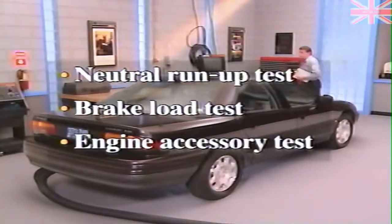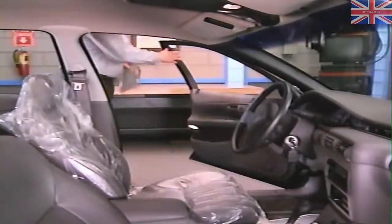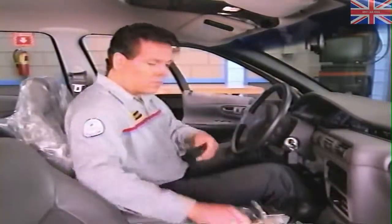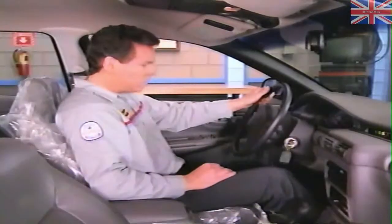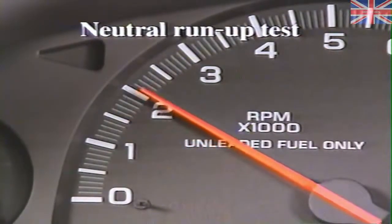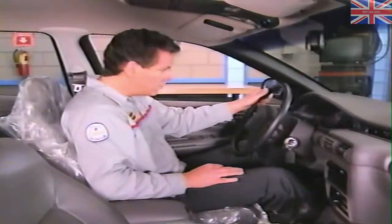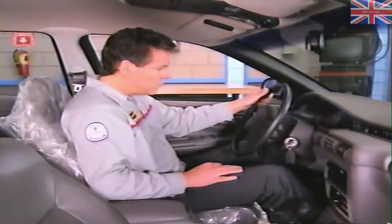The next three tests, the neutral run-up test, the brake load test, and the engine accessory test, are performed when you get back to the shop. The neutral run-up test is designed to identify engine speed-related vibrations. Use it as a follow-up to the downshift test or when the customer complains of vibration at idle. With the vehicle in neutral or park, slowly increase the engine RPM looking for disturbances that match the customer complaint. If noise or vibration occur, you have identified an engine speed-related problem. Note at what RPM the vibration occurs and obtain a frequency reading if possible.